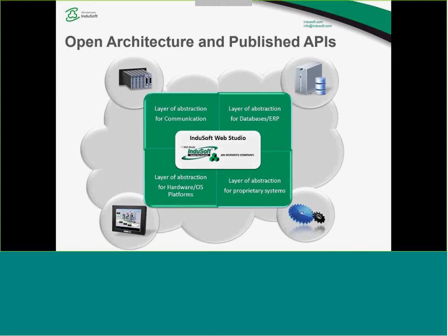The same application, the same InduSoft Web Studio runs on all those platforms, and you do not have to redesign the application or install different versions of InduSoft. If you have to communicate with different PLCs, we have drivers for more than 200 protocols, and you can easily switch from one to another, not having to redesign the whole application.